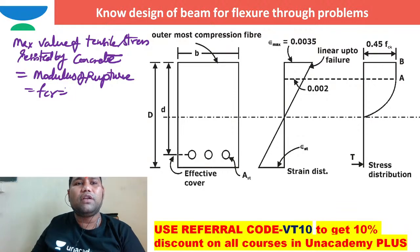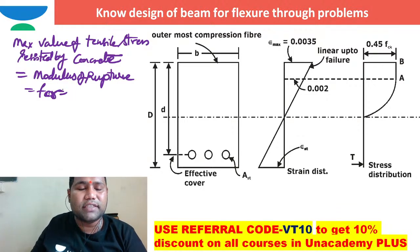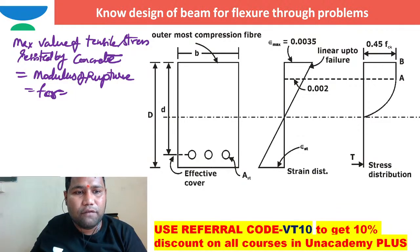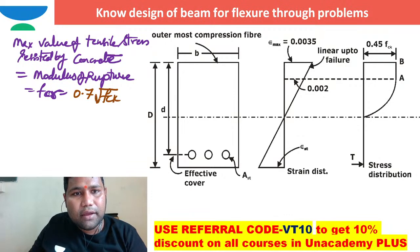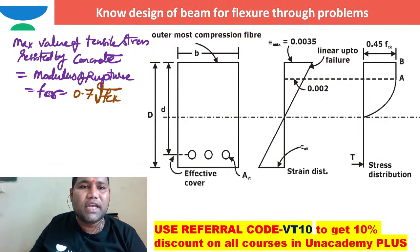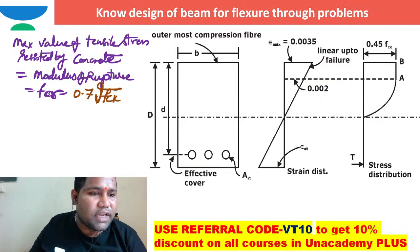How can we work out that FCR? If you have seen the code of practice IS 456, this modulus of rupture FCR is taken as 0.7 times root FCK. When compared to FCK, 0.7 times root FCK is very small. If you take FCK as 20, 0.7 times root FCK is almost 2 megapascal.